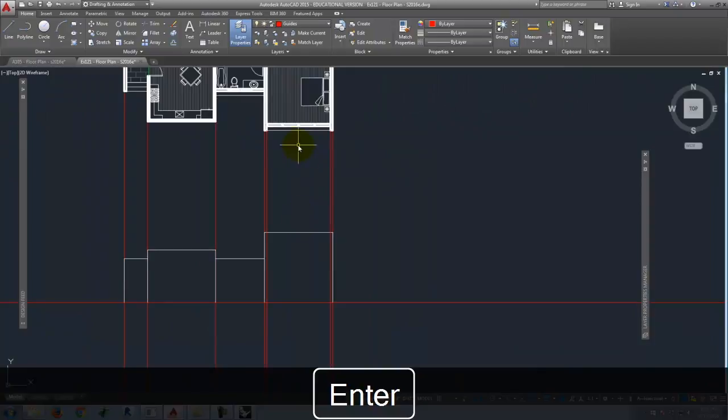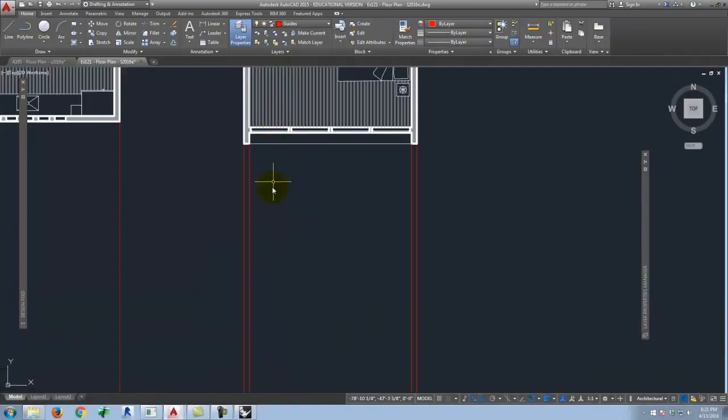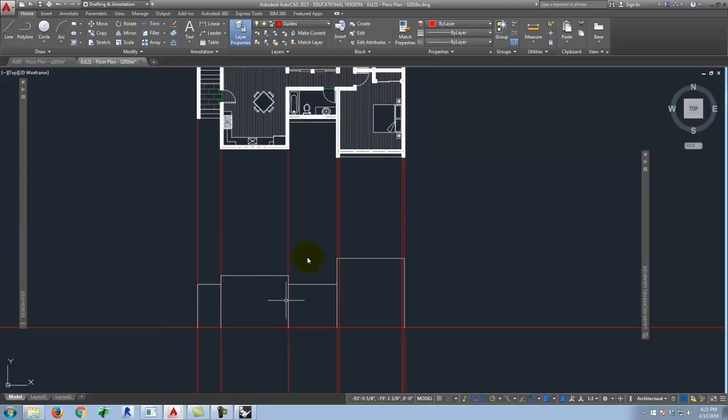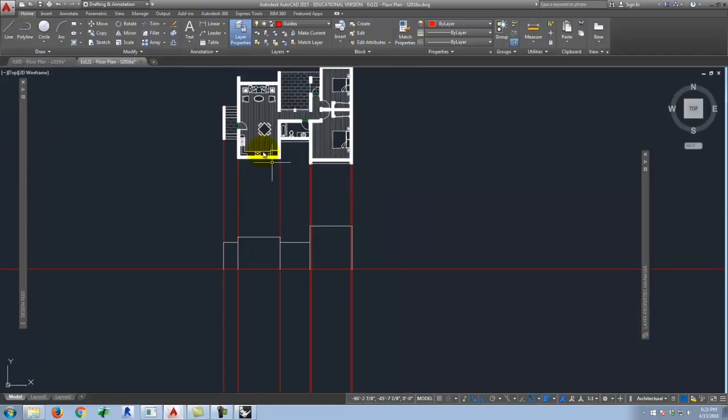Now, I would recommend when you're doing these sorts of things not going overboard in terms of drawing all the rays at once from every point. You notice that I did just the corners and I drew down on the elevation. Then I came back up here and I'm doing just these two lines and I'll draw. Then I'll add the center lines for the windows and then I'll draw. If I were to do all the guides at once, it would be hard to tell which guide corresponds to what thing. So it just helps to simplify a little bit.